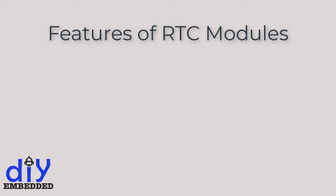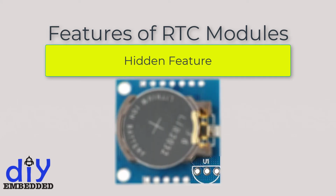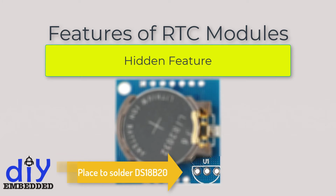There is also a hidden feature in the module. There's a provision on our DS1307 RTC module that often goes unnoticed. It allows us to install a DS18B20 temperature sensor. The 3 holes in the top corner right next to the battery holder, labeled as U1, is where the DS18B20 is installed.